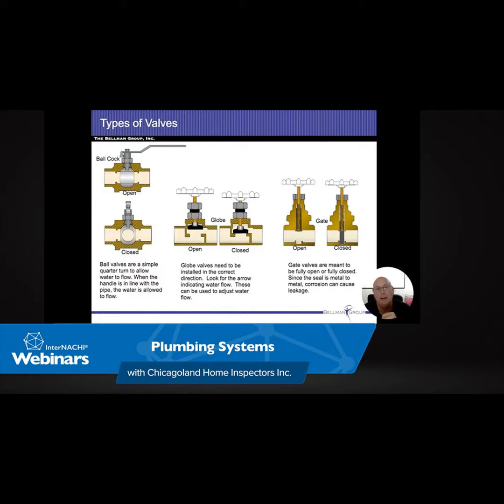So here's our initial setup. Water comes in from our well pumps it into our bladder tank, and everything works from there. So now the water's in the tank, we use it, we activate our pump, and you can see we're at 40 psi. The pump turns on, fills up our tank, builds up that pressure, gets to 50 psi, everything turns off, water flows, pressure drops, pump turns on, and that cycle just keeps going.